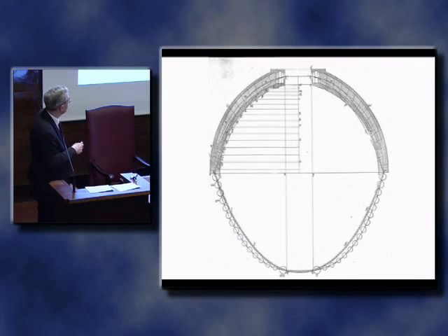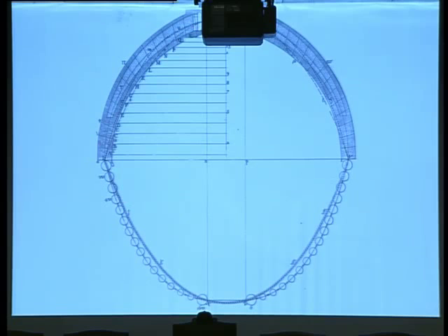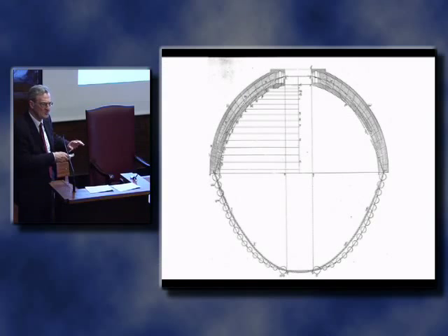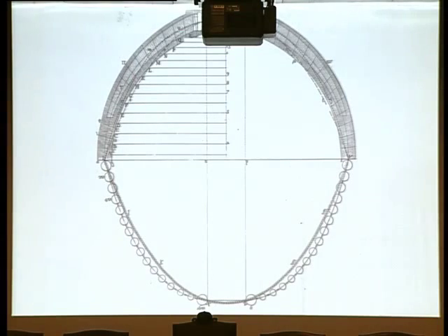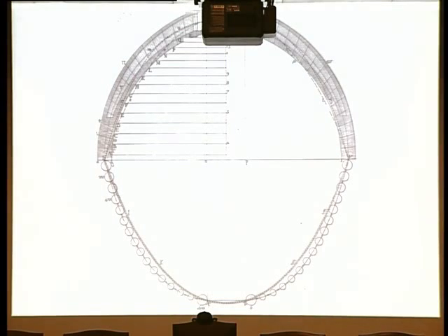was to make a drawing of the cross-section, to divide that cross-section into imaginary voussoirs, to compute the weight of each of those voussoirs, to make a ball corresponding to the weight and to hang those balls upon a chain, and to observe experimentally, then, what the line of thrust would be, that is, the hanging chain, which, when inverted, will give you the way the forces are carried within the arch there. So he finds this particular geometry here, turns this up, and says that is the way the forces are carried in compression rather than in tension in the arch.